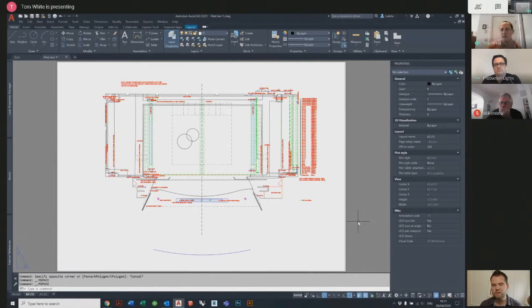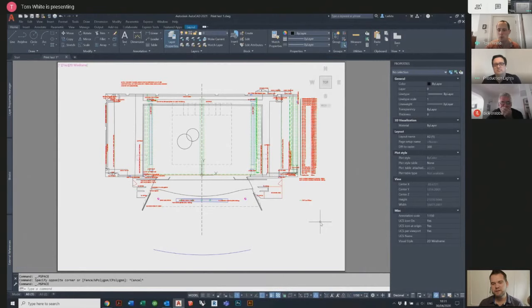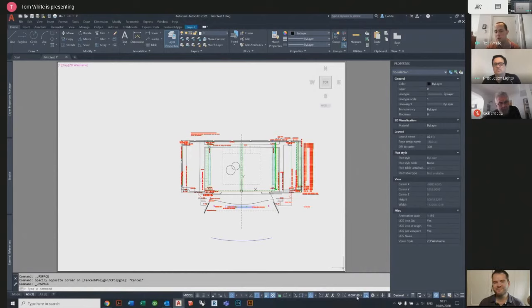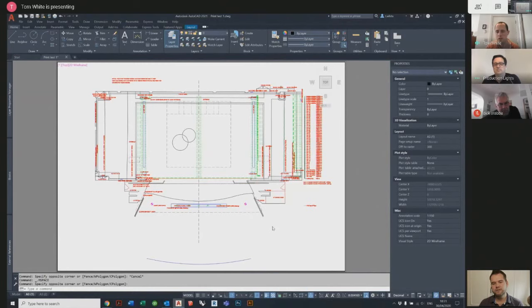That's a different thing? At this stage, it's frozen in time. Yeah, but I can easily, by accident or on purpose, edit it, and there is a way of preventing that. So if I double click within the viewport just below the command line at the bottom, you can see it's still 1 to 150 scale, but by accident I could do one click out and it's changed to an unusual scale. So I need to, within there, do zoom extent so it's centered to the page.